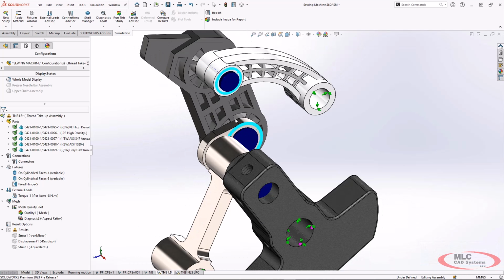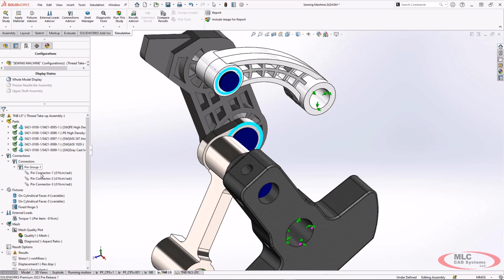But in this case, since there are two hinges in here that have no rotational stiffness, this can rotate and this can rotate, so that does add another degree of freedom. So it was able to recognize it in this case.